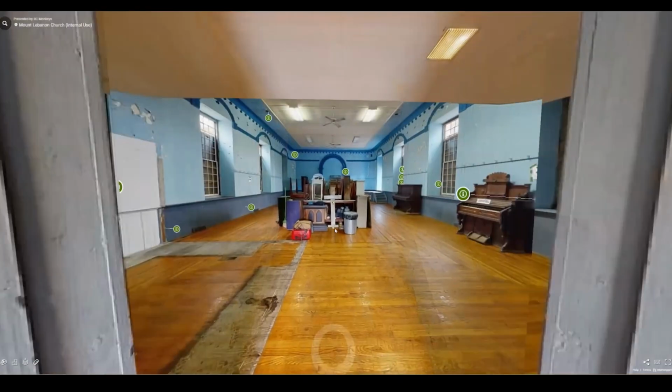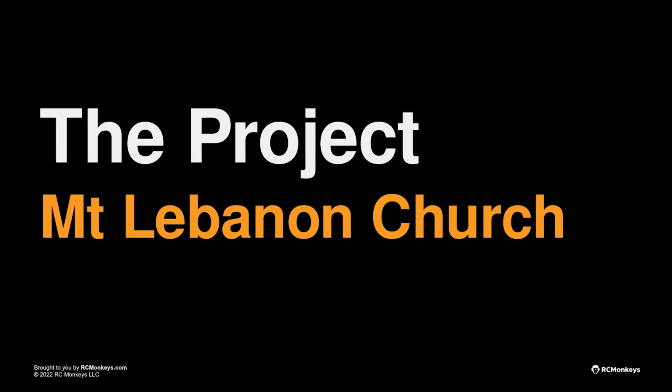But we thought, hey, this thing has a LiDAR, so let's test it and see if we could ever use the Matterport Pro 3 as a scanner. Can we rely on it? What accuracy can we get from the sensor? The specifications say we can get plus or minus 20 millimeters, but is that the case? Is the data noisy? We wanted to understand how the data looks when compared to another tool that we knew was accurate and gave us clean data.